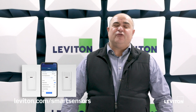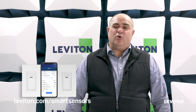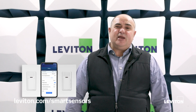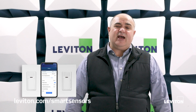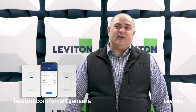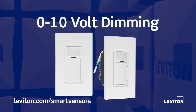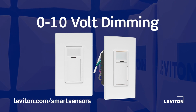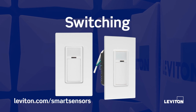A much nicer form factor. You don't have that bubble lens anymore. You have more of a streamlined look to the solution. And as I mentioned, as far as being code compliant, we definitely need to have that occupancy sensing and vacancy sensing abilities with it. A standard 0 to 10 volt dimming version of it has been our mainstay up to this point, as well as a switching version of it.